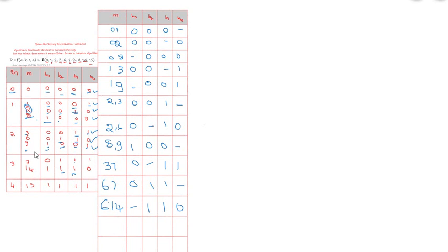Now move on to the 9. Actually 9 contains B3 and B0 as 1. So 7 does not have B3 and B0 as 1, so it is not possible in the comparison. 9 and 14: again, wherever 1 is present in 9, that is B3 and B0, it is not equal, because in 14 B3 is 1 and B0 is 0. So it is not equal. So 9 is not possible with either 7 or 14. Now 3, 6, 9 is over. 7 and 14 we used in different parts, so we make tick marks here.